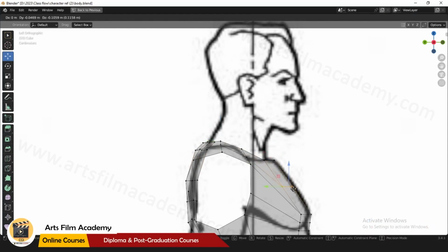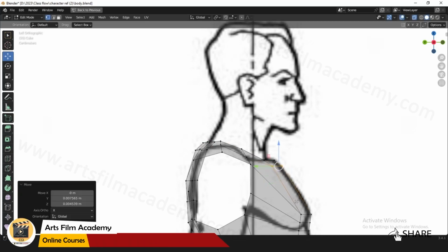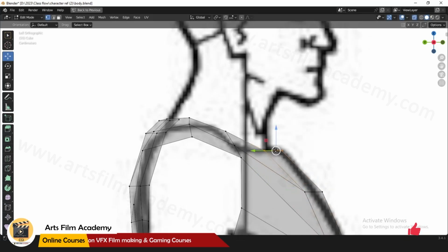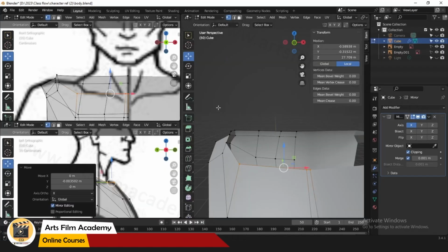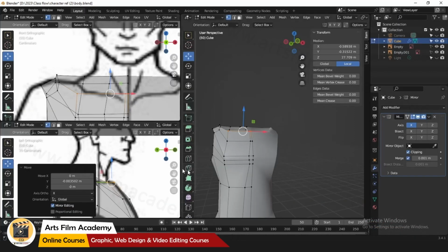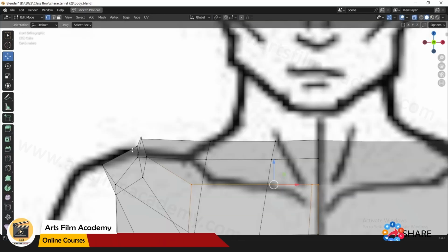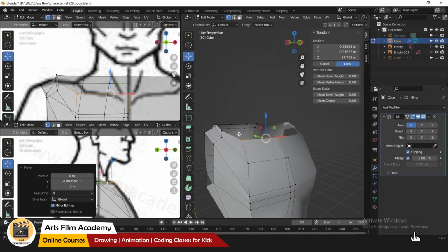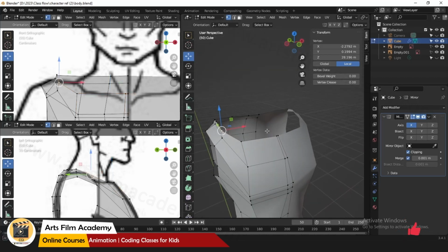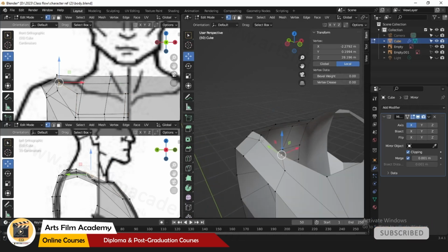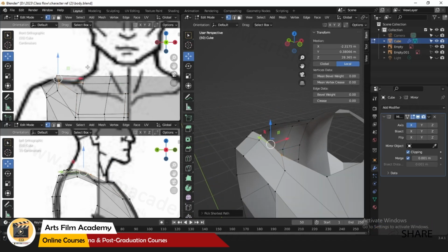So this you can keep it in center to balance, so there is not much poly here. So instead of adding in between, I am keeping this to the center. So we need to check even in this viewport what is happening. This vertex, okay, you can see here this vertex should go inside, right?